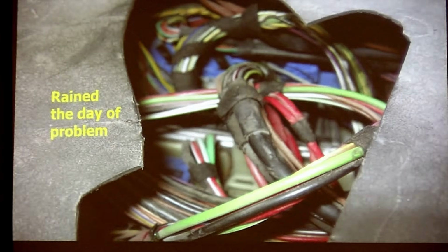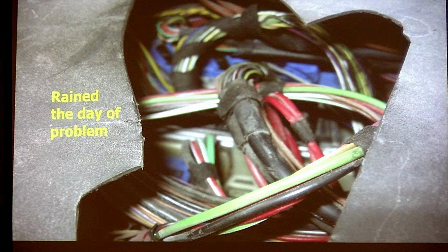Power grounds are good. Do you see that hole? It rained the day before. The rain got in there and smoked both of those. If you ever see one of these covers that's broken, you better fix it. Because that cover is probably about $50, and those modules were $4,000. And then you got to set them up. So, it's all what you want to do, but if you're working on a customer's car and you see any kind of a leak like that, you need to fix it.